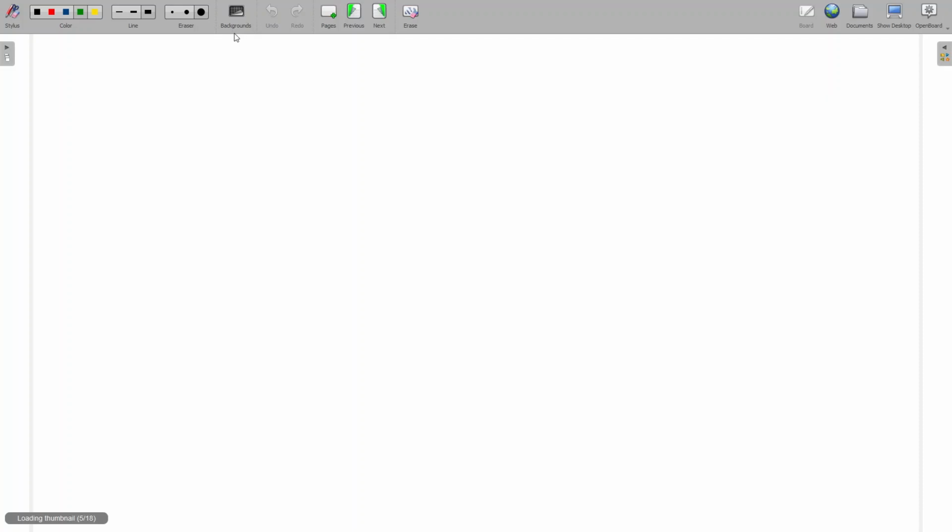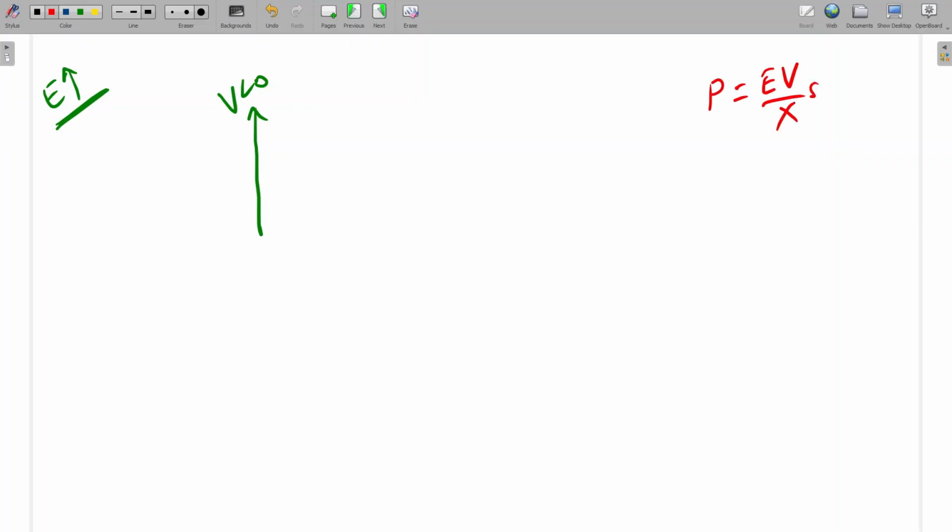Okay. So again I'm going to draw the phasor. This is V at angle 0. So E will be constant. Since excitation is constant, E will be constant. What is the equation? P is equal to EV by X into sine delta. So since load is increasing, E is constant, V is constant, X is constant. So what will happen? Delta will increase.